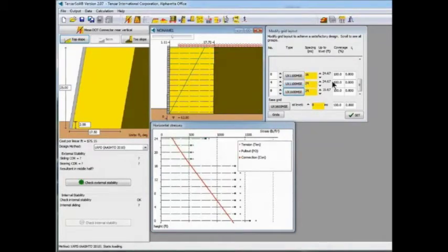And now let's separate out the top 2 layers of geogrid so we can reduce the percent coverage on just those 2 layers. So we'll take out 2 layers of geogrid and then add a separate group up above at 24-inch spacing. And now we can reduce the percent coverage down to whatever the repetitive obstructions equal out to. So let's say it's an 85% coverage. So maybe some guide rail posts at a repeating interval. We'll click Set.